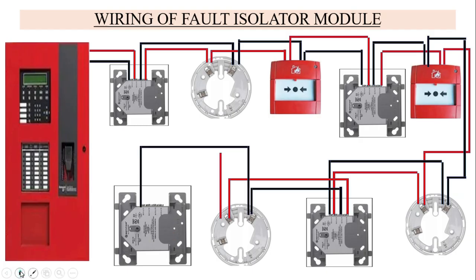At the last terminal, when the loop circuit is coming back and returning to this panel, at that last point we must always install the isolator module.